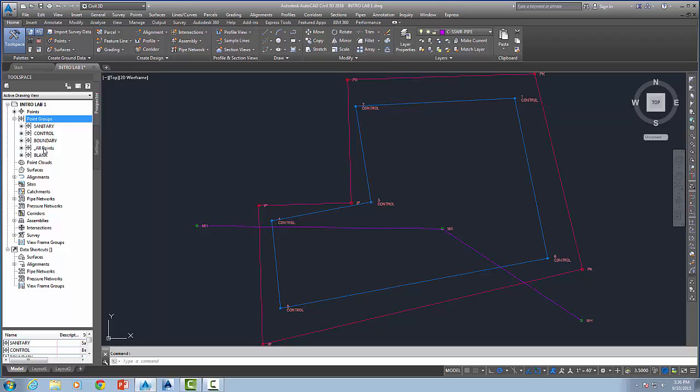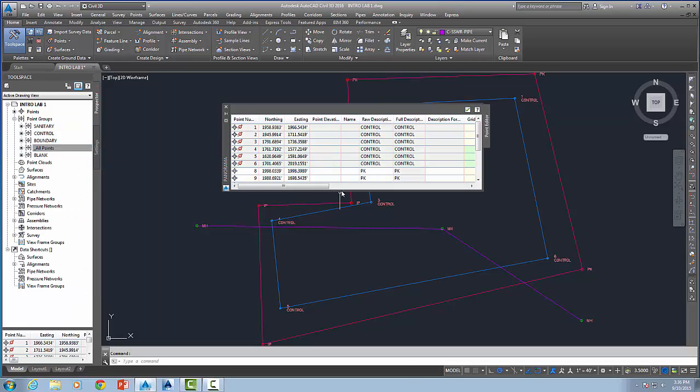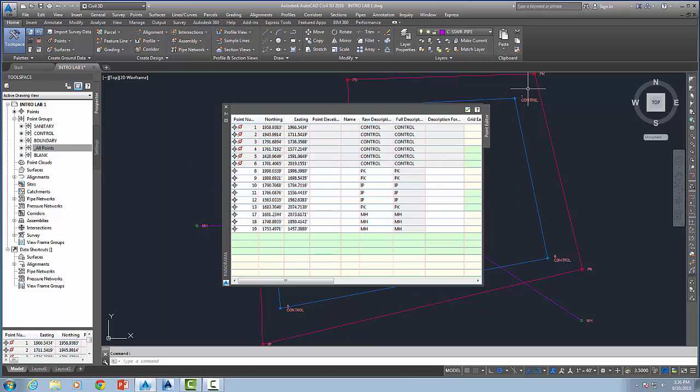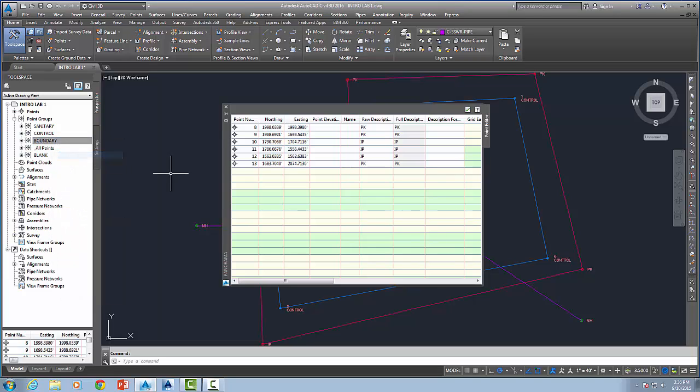And we can view things. If I go here and look at edit points, I can open up the panorama. I can edit points within this, and notice this is showing me everything that's in my project, and I currently have these locked because, as I explained before, I don't want to inadvertently grab one and move it. Eventually on any project I would probably lock a lot of them so that I wouldn't mess with that. We can fix things in here, we can manipulate them. If I look at this group and look at its edit points, notice it's just showing me the ones associated with that.